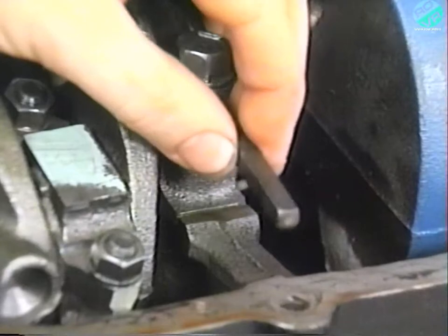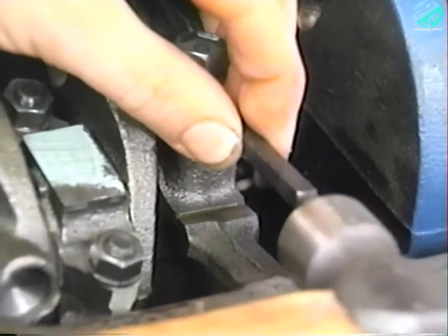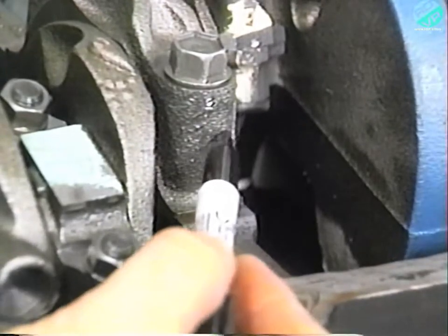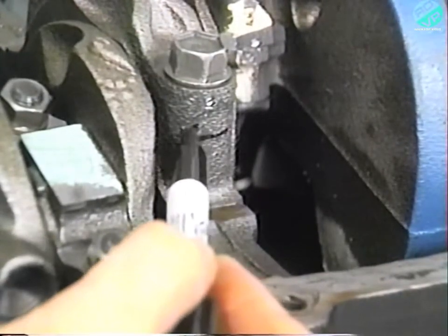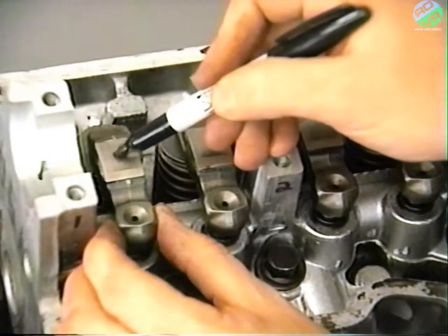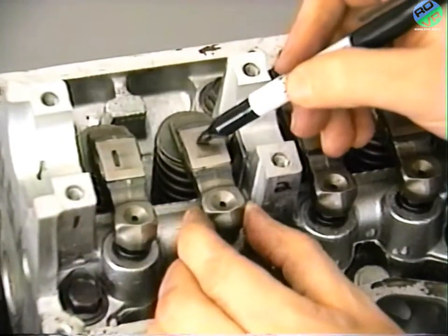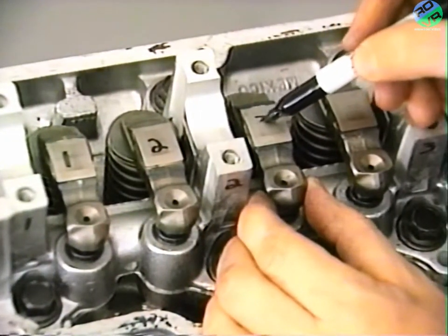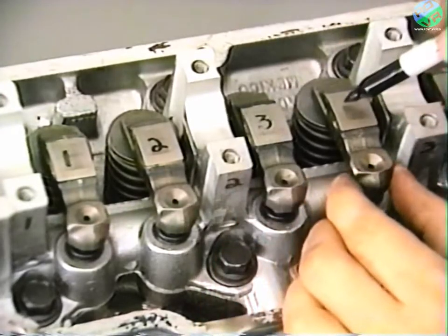An important part of any professional engine disassembly is the correct marking of engine parts. Components, such as bearing caps, should be number stamped before removal. If the proper direction of installation isn't indicated, add an arrow. Also, valve train components, particularly rocker arms and lifters, or cam followers as in this case, must be numbered and kept in the proper order for reinstallation.